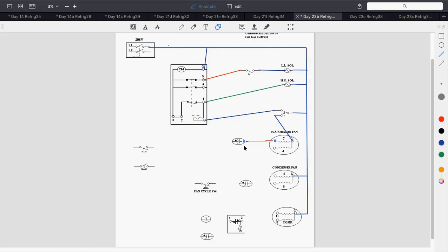It will have like 2 or 3 wires on it that you're going to use as a junction point. Doesn't mean it's in series with the run winding. But if I take my power feed, I'm going to wire there. I'm just using that side of the capacitor as a junction point. Everybody follow? Yeah. Okay, and again, we're thinking in a unit. This is how it's going to show up.